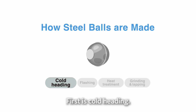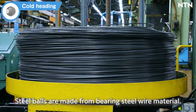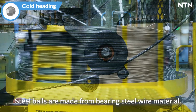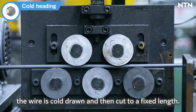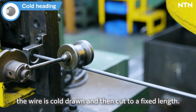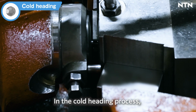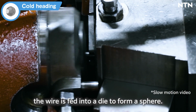First is cold heading. Steel balls are made from bearing steel wire material. In the cold heading machine, the wire is cold drawn and then cut to a fixed length. In the cold heading process, the wire is fed into a die to form a sphere.